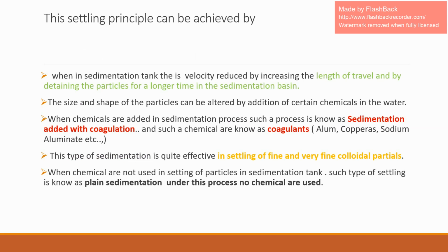In a sedimentation basin or tank, the velocity is reduced. When velocity is reduced, it increases the travel time, and the detention period here is of a longer time.